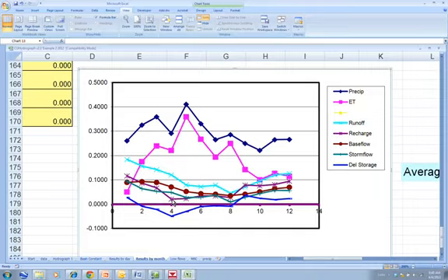And so the recharge is less than the base flow. So that means that you have more flow coming out as base flow than flow coming in as recharge. And the only way that that's going to happen is if you're removing water from storage, and that shows up here as this change in storage. So it's all internally consistent.